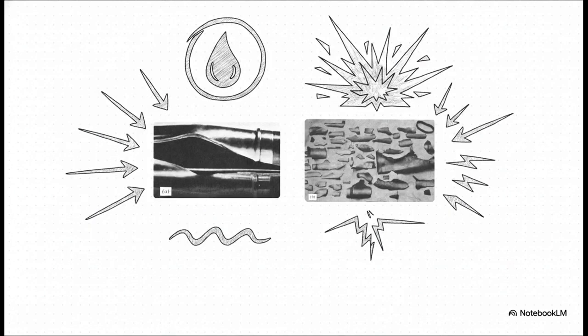Scale this up to industrial pipes and the stakes become pretty terrifying. The ductile failure on the top took a massive hit of internal pressure, but look closely. It's still in one continuous piece, even after all that deformation. The brittle pipe on the bottom, though, completely shattered into countless sharp pieces. In pipeline engineering, a brittle failure isn't just a leak. It's basically a massive, high-velocity shrapnel hazard.